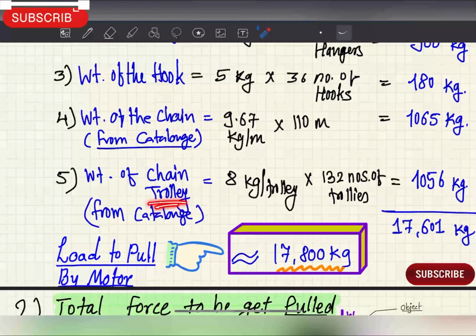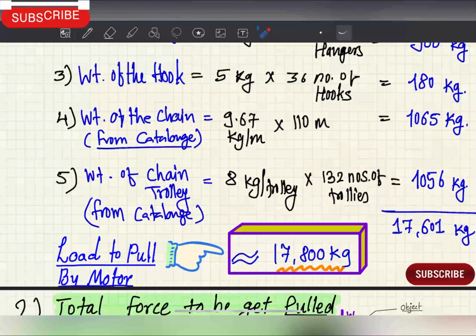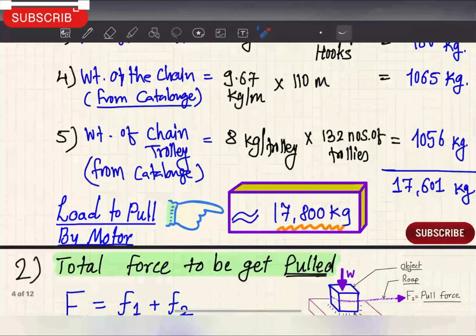So weight of the trolley from supplier catalog. We need 132 number of trolleys to carry this chain effectively. So 8 kg weight per trolley into 132 numbers comes to 1056 kg.